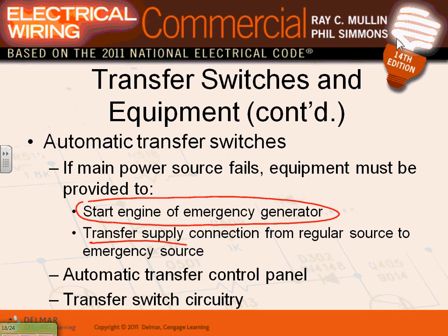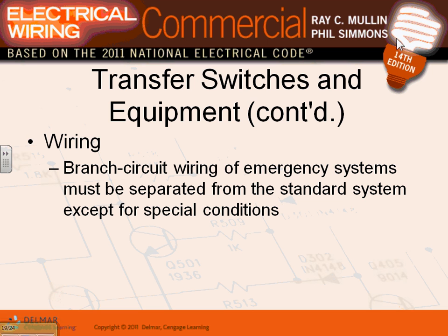Okay, so with the transfer circuitry, guys, the transfer switch circuit, if it's an emergency transfer switch, everything related to the transfer switch is emergency. So the control circuit has to be separated in a different conduit from the power circuit and so forth. Any questions, guys, about the transfer switch that comes with an emergency or legally required standby system? The job of your auto transfer switch is to start your generator and transfer you to the other side.